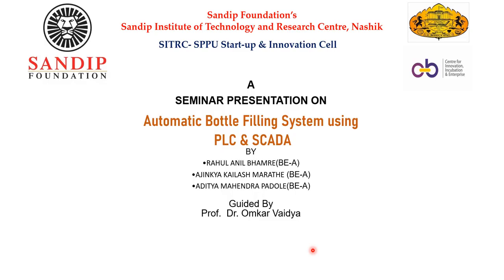Today I am here to explain the automatic bottle filling system using PLC and SCADA. So, what do you mean by PLC? PLC is a programmable logic controller, a device which controls the given system. And SCADA means supervisory control and data acquisition system, which means you can monitor your system by using SCADA.